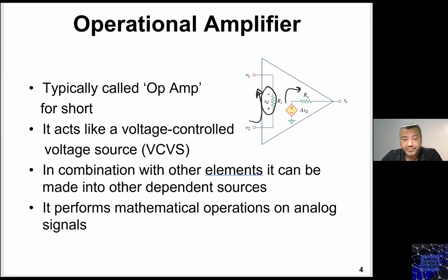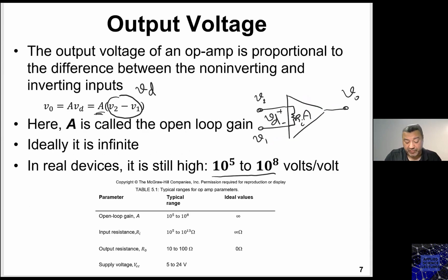Is this clear? In this case, V2 is the positive voltage. That's correct. V2 is the positive, V1 is the negative, and this is what we also have here. But here we're looking at the operational amplifier being flipped. So here we have the V2 up and the V1 down. So don't let this one confuse you.